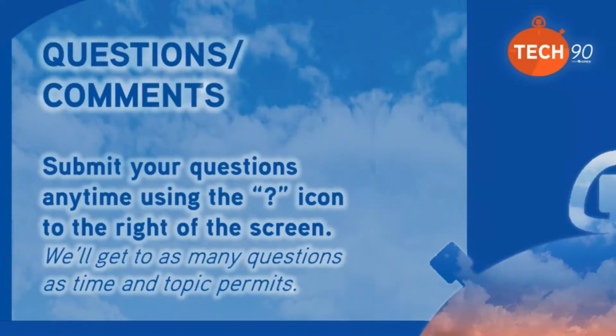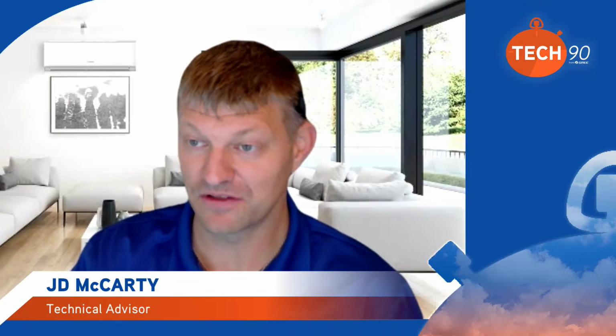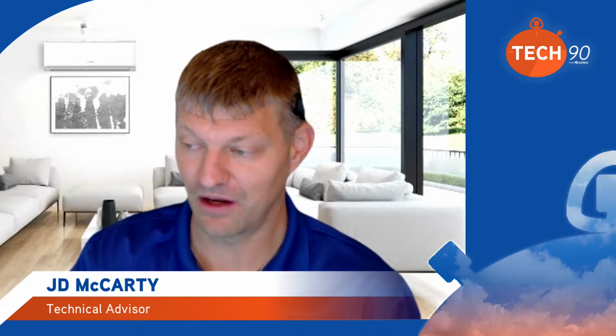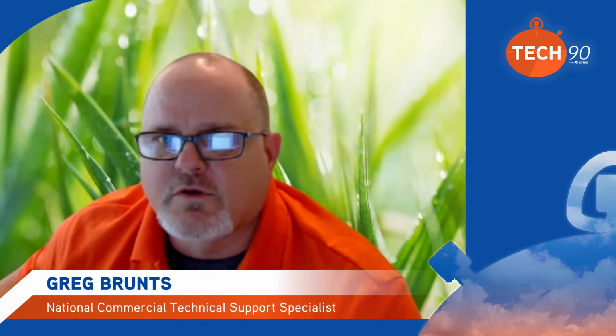All right. Any more questions, JD? No more questions, but just a comment from Steven. He did say quality of the copper might affect your flare, so that is a good point. Be sure to know where you're getting your copper from and get some good quality copper. Some of it can split if it's not quality copper when you're trying to do your flares and flaring that pipe. So that's a good point to keep in mind. And that's the other reason for a visual inspection, making sure after you flared it, it didn't split. You don't have any problems with the flare itself.